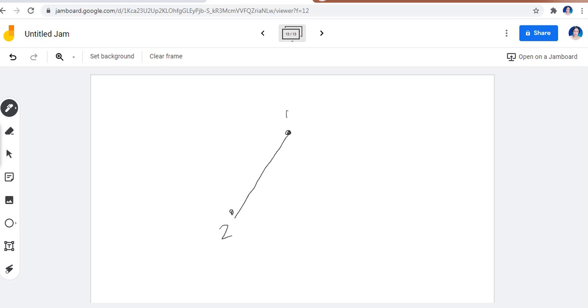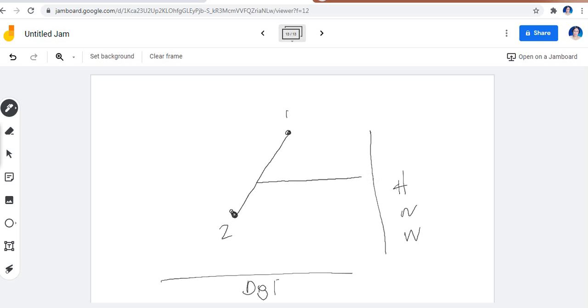You have the initial state, or you can use the humidity that you have and the dry bulb temperature. So you have here dBT, and you have here your humidity H, or it could be W. So using any of the two values or the conditions that's stated in the problem, you'll have this 2. Now, since you already solved for the H3, that H3 you find here. And then you project it here. Now, you read the dry bulb temperature here. So, this will be the dry bulb temperature T sub 3.